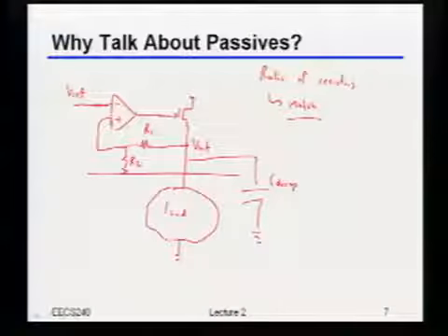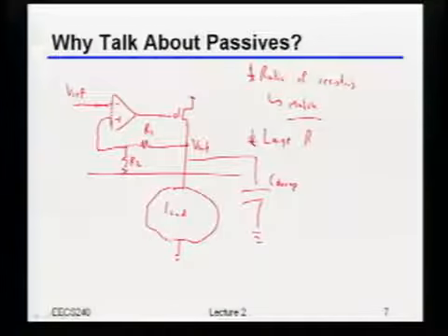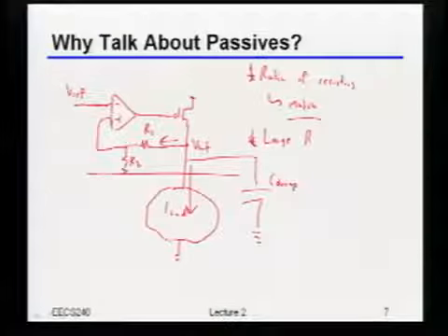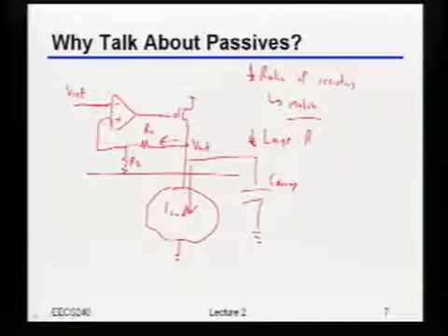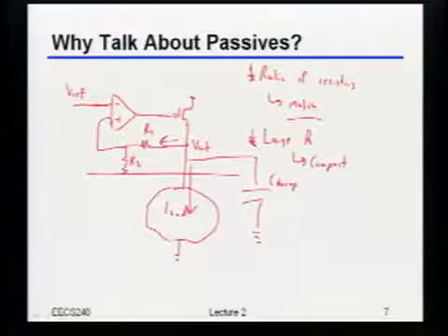Large. Why do you want them large? Prevent high current. Yeah, because the actual current I want is over here. Any current flowing over there is just wasted in some sense. So generally speaking, I want those resistors to be pretty large. Now, do I want to spend the entire area of my silicon chip to get a giga-ohm resistor, or even a mega-ohm? What do you guys think? No, right? I want the actual load. My regulator is just something off on the side that's making the thing work. So not only do I want large R, but I want it to be compact.